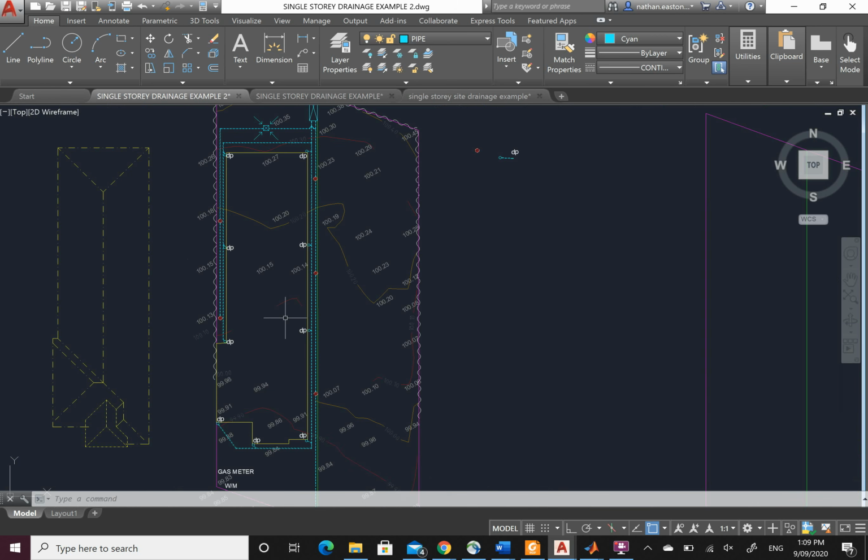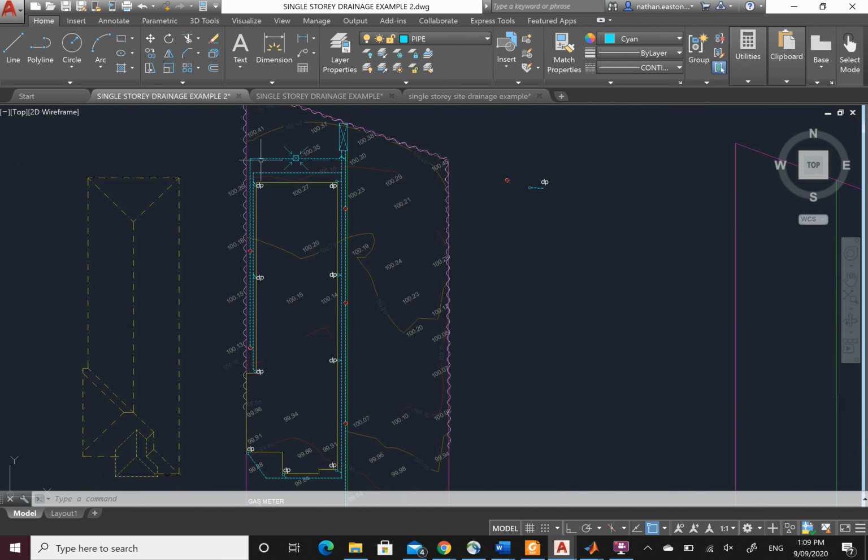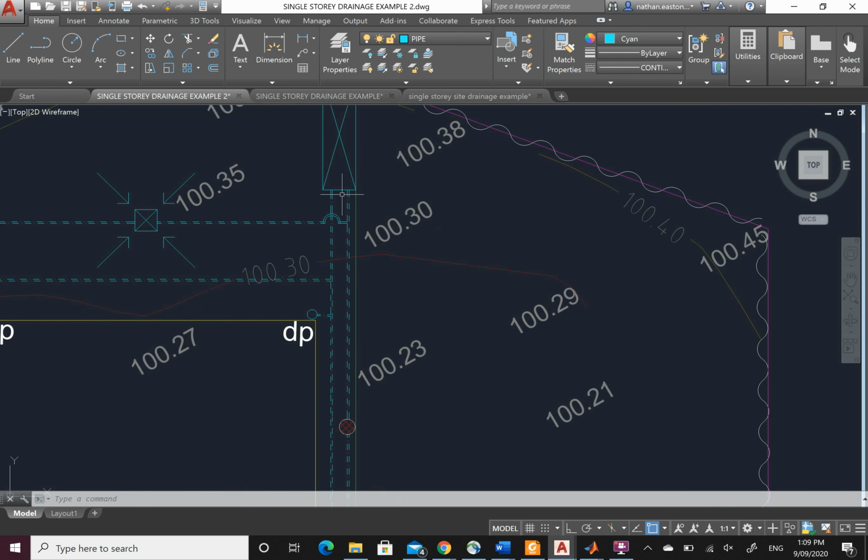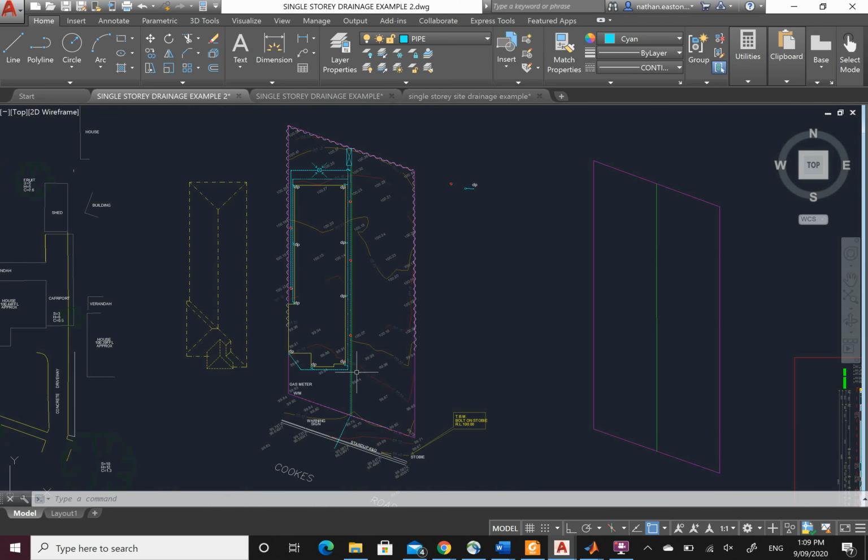We've got annotations and levels and stuff we have to do. Well, let's go ahead and do the levels now while we're here. Just a quick recap. I have the water hitting the roof, runs down our downpipes, which is this line here, runs to the tank. After it hits the tank, it discharges the entire way, runs down and comes out at the street.